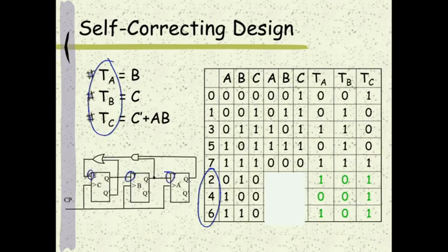And it happens to be these three values here. And then based on the functionality of the T flip-flop, once I have a 1, I need to flip, and when I have a 0, it stays with no change. So that is how I do this circuit analysis.